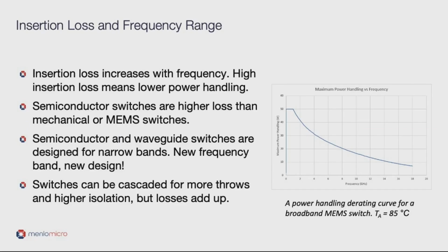The last consideration relates actually to the isolation of the switch, another key spec for high power applications. Isolation can be increased by cascading switches, and that will also increase the throw count, but those losses do add up, particularly if you're using a lossy semiconductor switch.